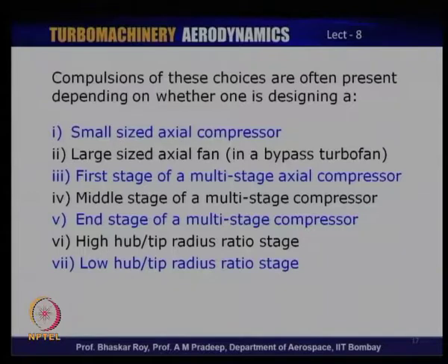The blade design law of such a large sized axial fan would be quite different from that of a small sized axial compressor. The first stage of a multi-stage axial flow compressor, which is likely to be a comparatively large size blade, would be different and would probably use a different kind of design law